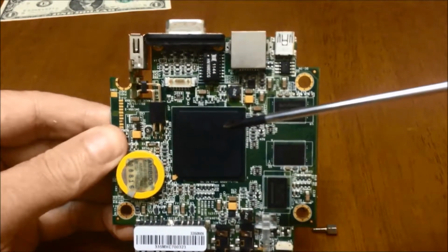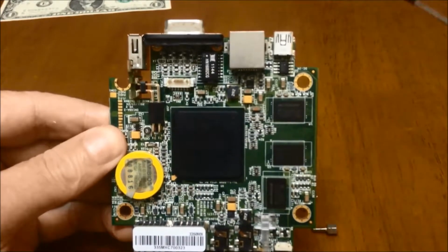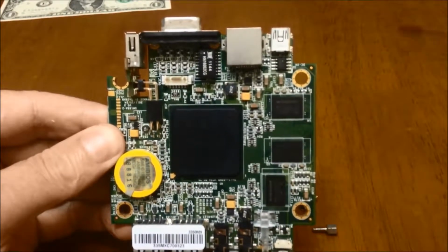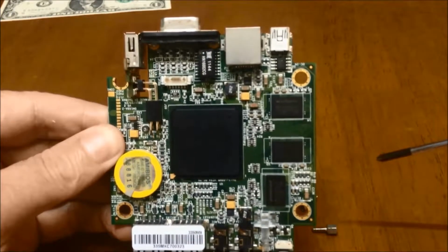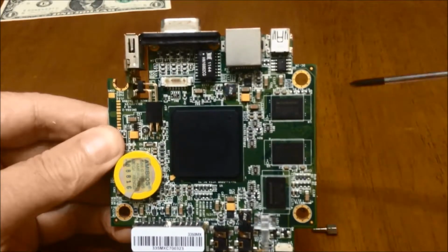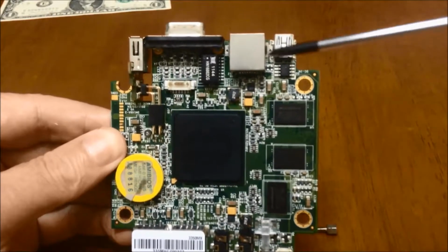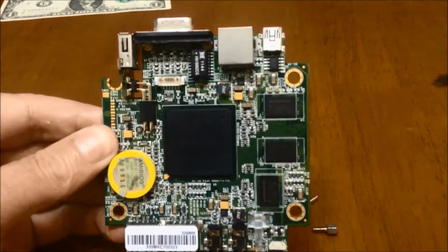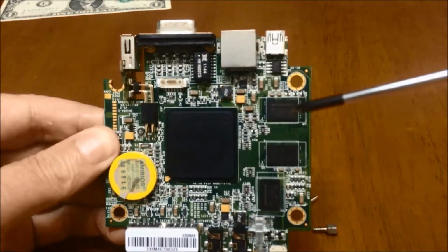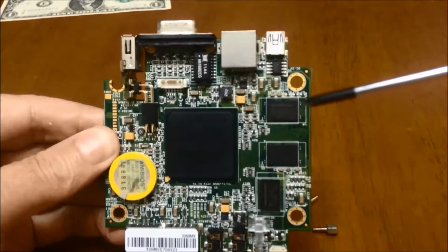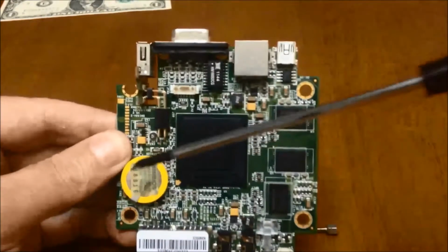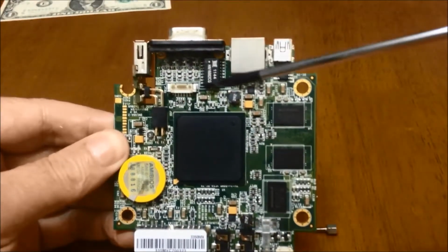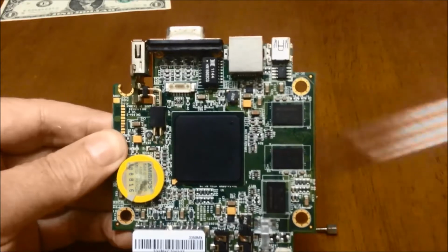If you look on the top side, we've only got one major component. This is a system on a chip, and it's basically got everything on this particular chip, including IDE, serial ports, floppy port, all kinds of peripheral ports that you'd expect on a PC. We have 2 chips here, which gives us 256 megabytes of DDR2 RAM, battery for a real-time clock, of course, and then the Ethernet IC.